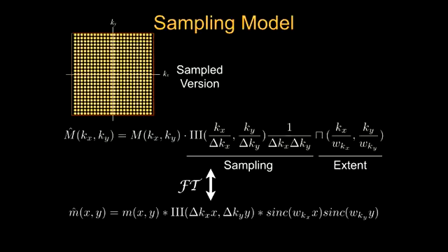That means the field of view is much smaller, so you have a folding over artifact. Here, the sinc is basically giving a blurring. If the main lobe of the sinc is wide, you're convolving with the sinc function, so your actual signal will be blurred.